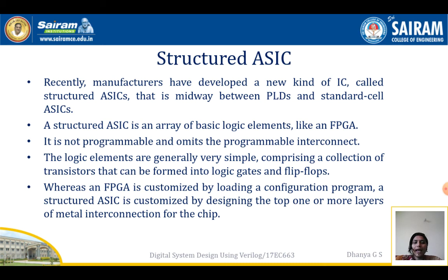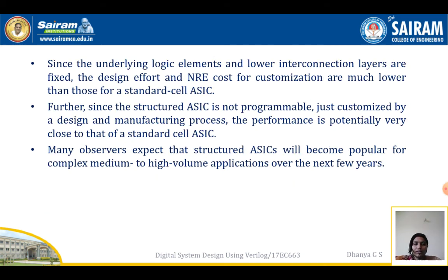flip-flops, whereas an FPGA is customized by loading a configuration program. A structured ASIC is customized by designing the top one or more layers of metal interconnection for the chip. Since the underlying logic elements and lower interconnection layers are fixed, the design effort and NRE cost for customization are much lower than those for a standard cell ASIC. Further, since the structured ASIC is not programmable, just customized by a design and manufacturing process, the performance is potentially very close to that of a standard cell ASIC.